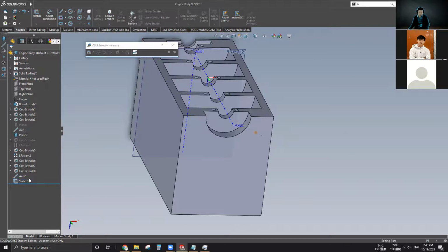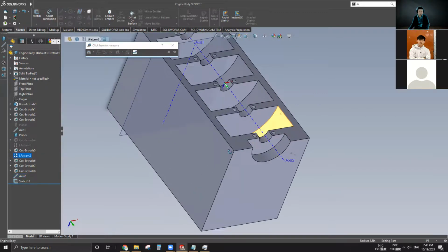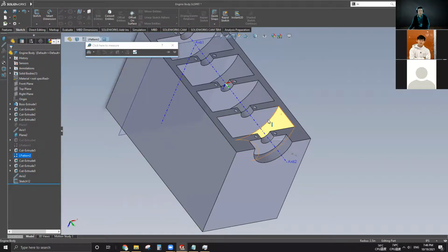However, there's a limit because the axis is made by this feature, right? We use this feature as a reference to make this axis, which is right here. This axis cannot be moved on top of its own reference feature. So right here, you can see my cursor became invalid, right? But anything after that, I can move anywhere I want. So that's the only restriction.